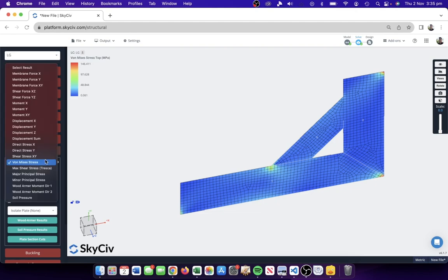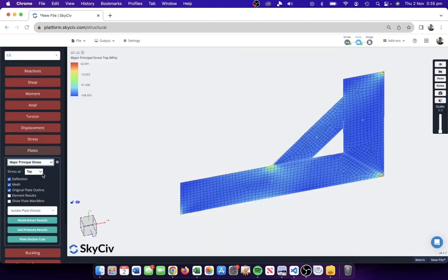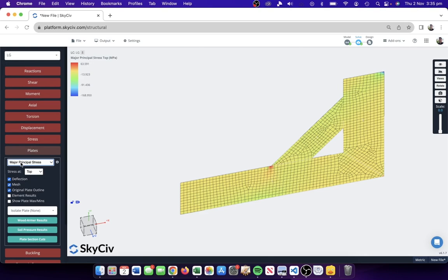We also have some major and minor stress, principal stress results, and you can see one of the larger stresses that we're seeing is around 160 megapascals. And I can have a look at the material used. Two things I want to look at: one is the material used to see what the ultimate limit and the yield limit is for that particular material.